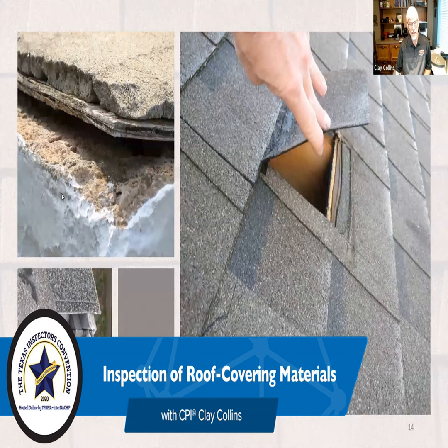The underlayment must be parallel to the roof. That underlayment can't go vertically because you have more opportunity for water to migrate under those laps. And they put an awful lot of fasteners here, but that's not a substitute for correct installation. And since you can't install it vertically, you really can't install it at an angle either.